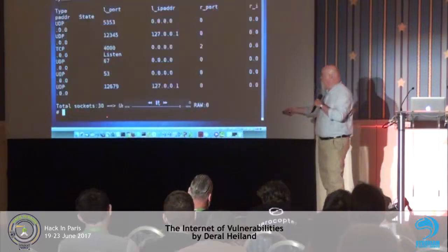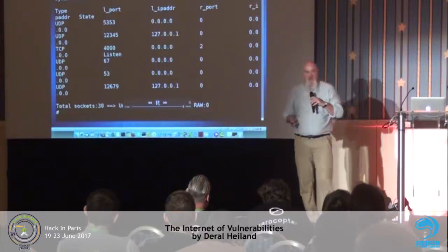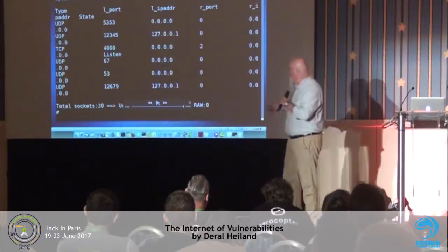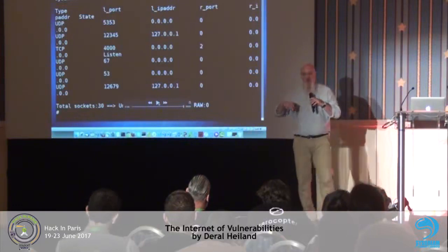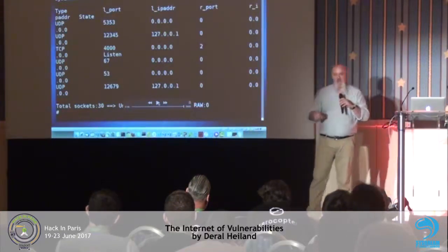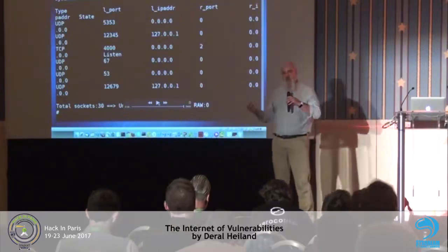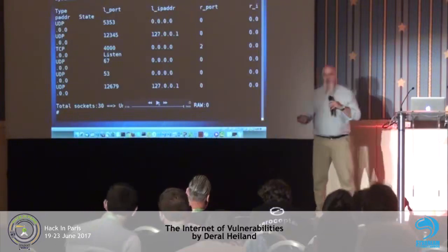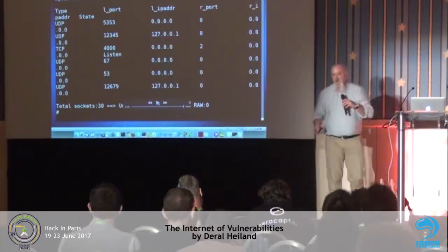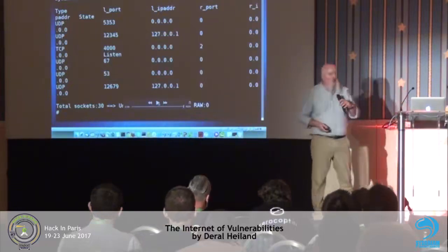It had several command structures. They're fairly simple, maybe 5 or 6 commands you can do on the device. This was all you could do. We pulled the firmware off the device. The firmware came down encrypted, but once it landed on the device, we tried reading it straight off the device and failed, so we desoldered the chip, a standard SOIC-8 chip, and were able to pull the firmware off of it and look through it. Again, we didn't find anything great other than what you already saw flow by.